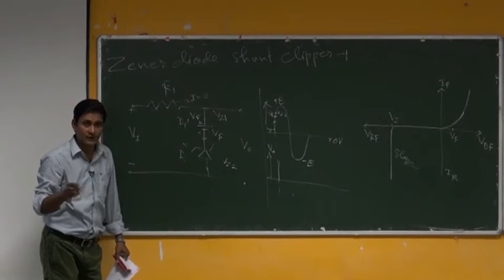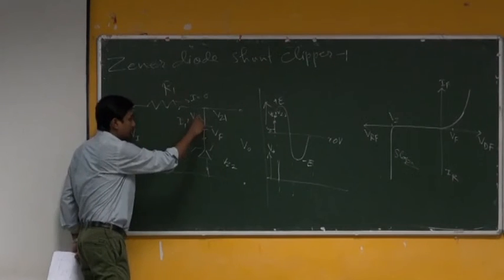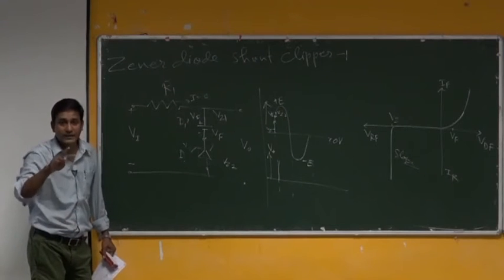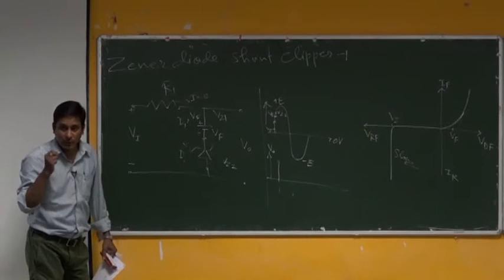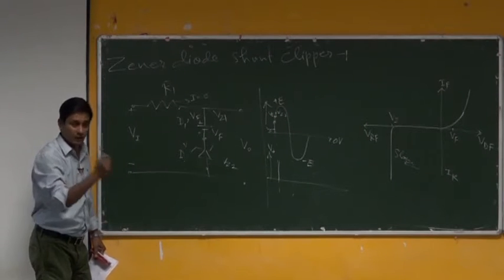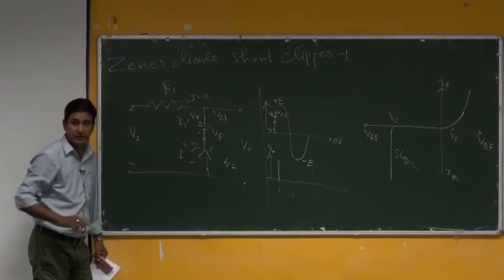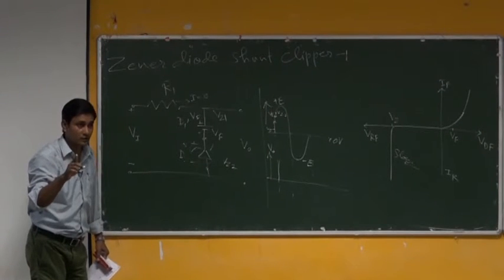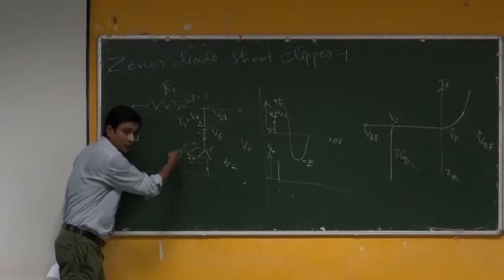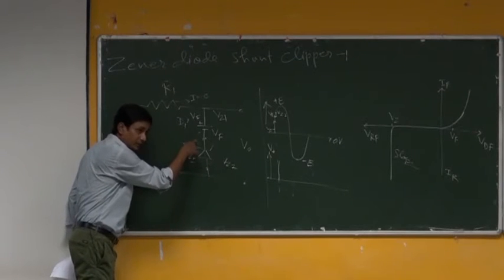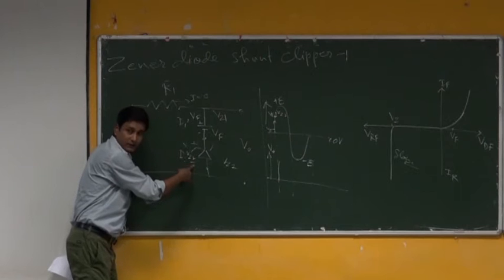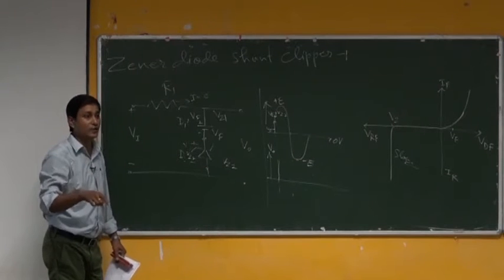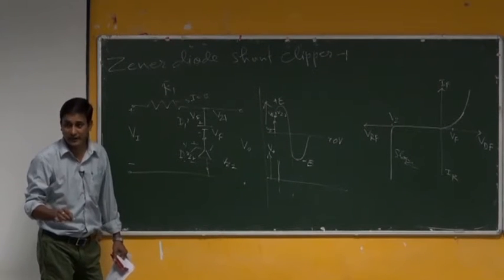Why is it so? The reason is that the potential is coming plus minus here, but here the configuration is such that the polarity is not satisfying positive to the P terminal, negative to the N terminal. So it is positive, it is negative of how much? Vz2 or beyond. Say Vz2 voltage has come there with positive side here, negative side here. That could make this diode reverse biased, and since Vz2 is the breakdown voltage, it will start conducting.